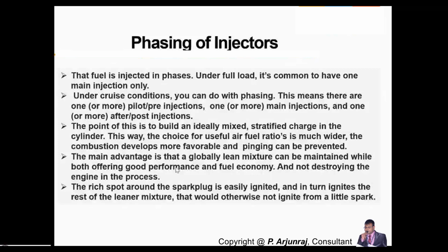See again, whatever the pilot, main, or delay injection, it will also vary with respect to the speed and also engine load. And one such phenomenon when you're going for the phasing of injector under full load condition, it's common to have one main injection only. When you're going for a full load, and the torque of the engine is higher, then you can have only main injection.